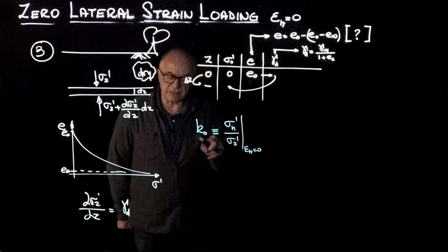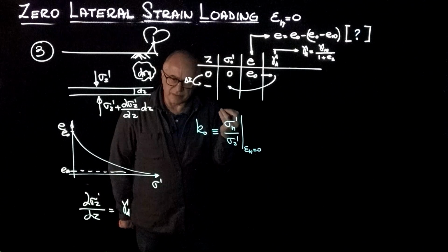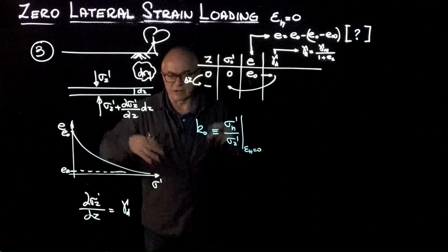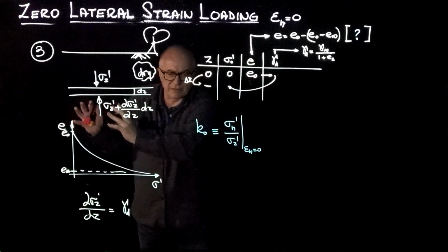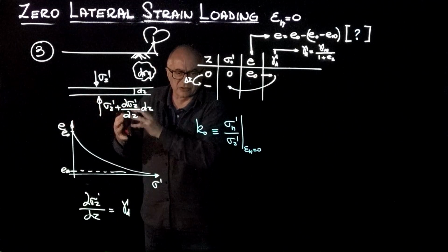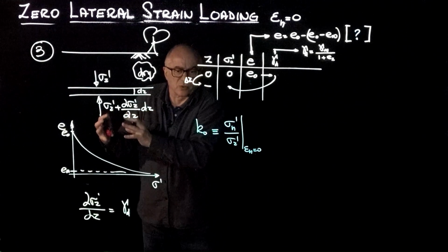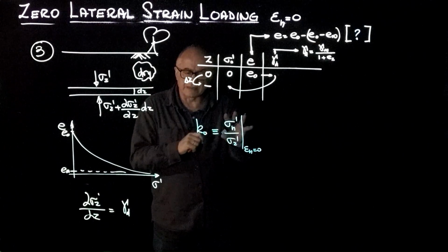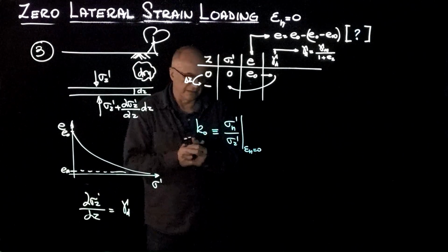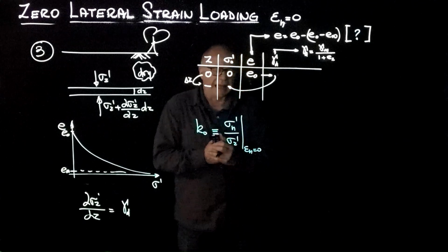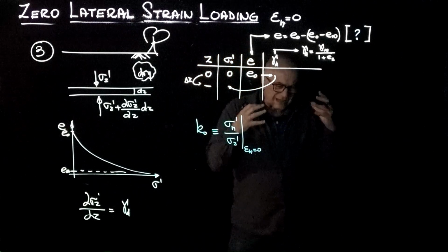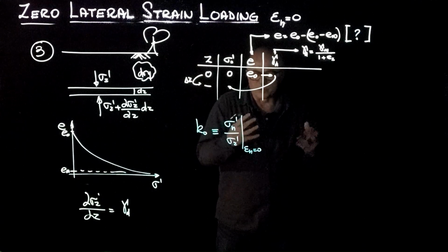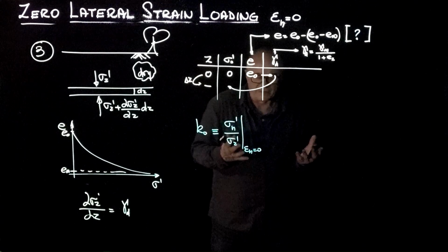So this is a definition. And please, it's very important to realize that this is a ratio of effective stresses. It cannot be total stress because the water is doing one thing. According to Pascal, the horizontal and the vertical pressure in water is equal, the ratio is 1. However, the granular skeleton, because it's frictional, is doing something else, which is what K0 explains. And this is Jaky's insight. If you look at his data, the original data is pretty much between 0.4 and 0.55.